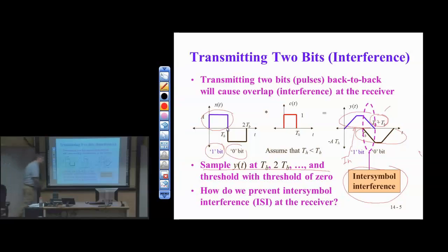And I can send that back, and then communicate over a control channel that's really low rate, very reliable. So I can send back over the control channel the estimate of T sub H. Now, that's one way to do it. In practice, many standards simply hard code that value and figure out what's the maximum T sub H that they see in the field, and they just make that part of the standard. This happens in DSL, in power line communications, some Wi-Fi standards. So it's a pretty common deal, if we need to know this delay.